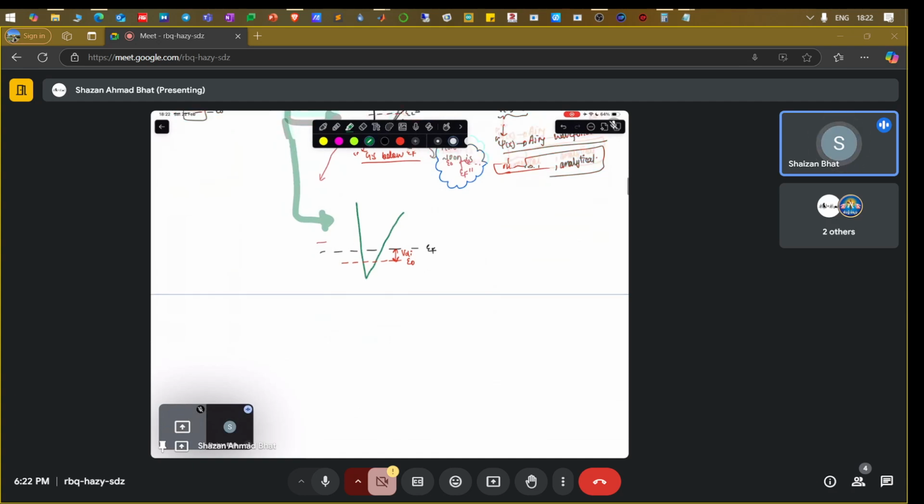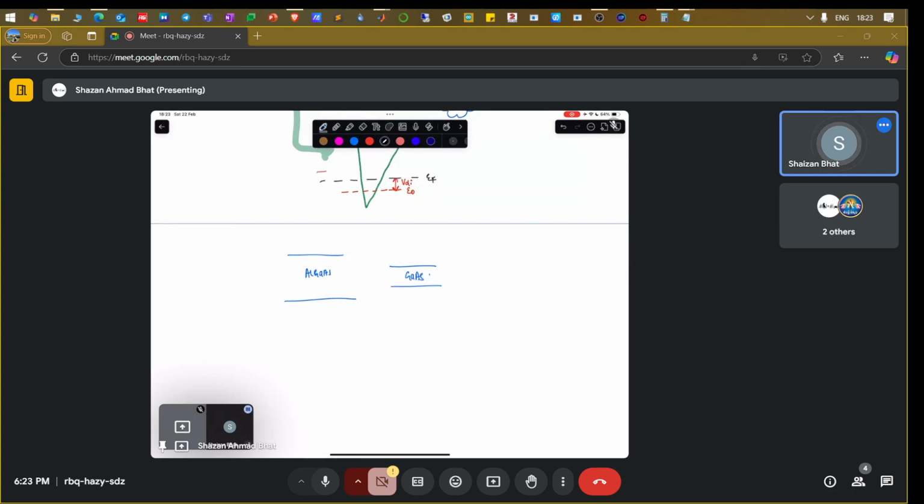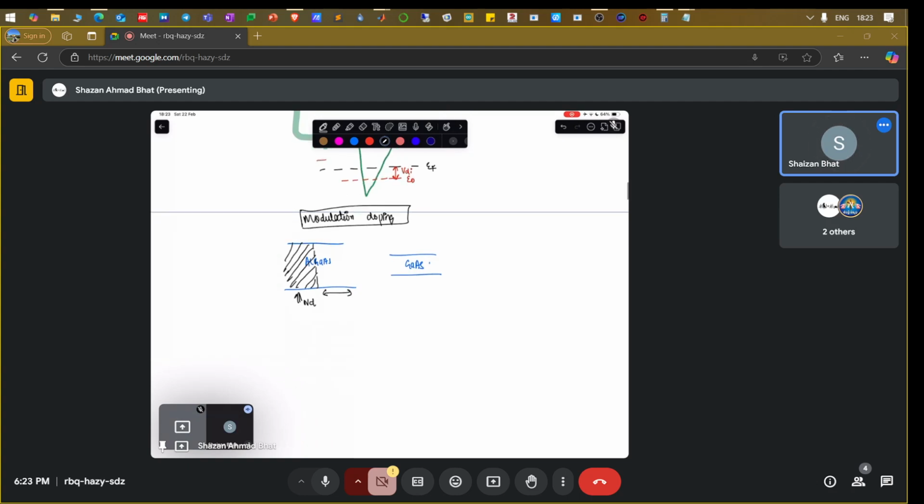Now, when you have AlGaAs and GaAs, you can dope it with certain material, something called modulation doping. What is modulation doping and why is it necessary? You dope this particular section and leave this other section without any doping. So you dope it with Nd, whatever the N plus doping is for aluminum gallium arsenide, and you leave the other section undoped.